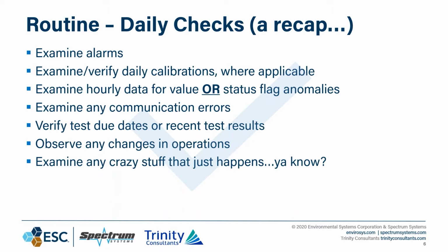Now previously, we had talked about our daily routine, and this is just a recap from last week's webinar, part 1, where on a daily basis, we believe that as a best practice, you should be examining your alarms, that you should be examining and verifying the nature of your daily calibrations where applicable. You should be examining your hourly data for both value and status to look for any anomalies, anything that looks a little out of the ordinary.